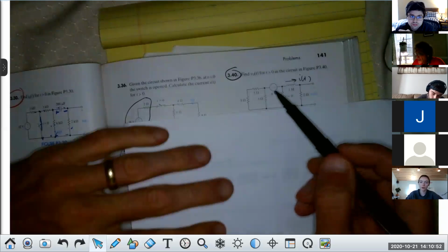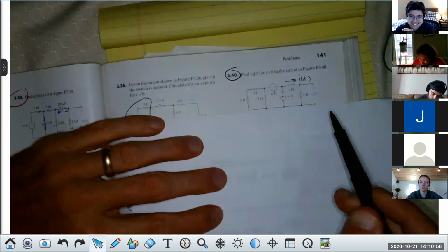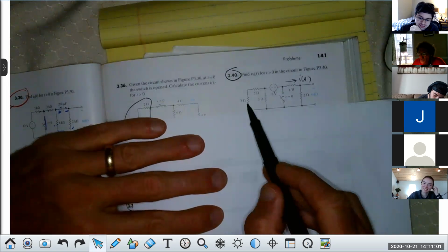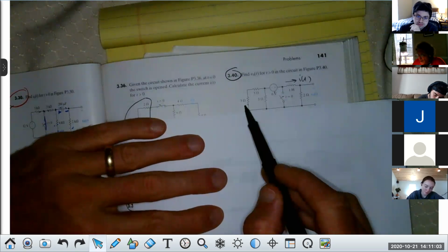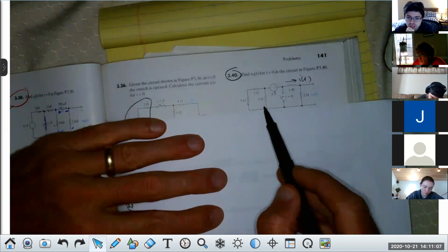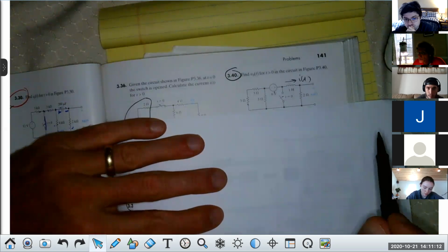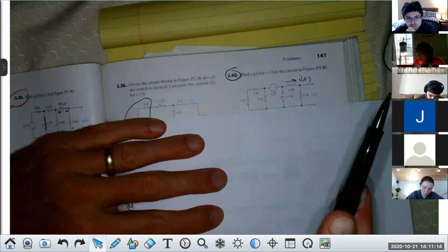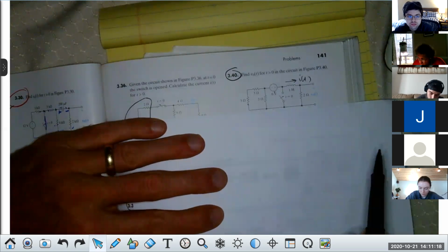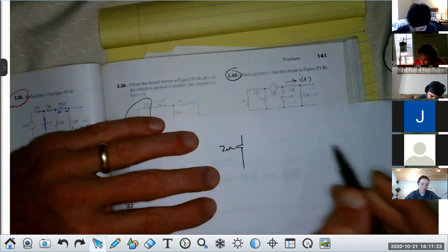The more heads that are actually alive, the better. Jessica, I don't know what's going on, but thank you for your thumb. That's good enough. If I see this, I'll make that 6 ohms. Do you all see that? I have 6 ohms. Do you all see it's in parallel with 3? So if I have 6 in parallel with 3, isn't that 2? 6 times 3 is 18. 6 plus 3 is 9. 9 into 18 is 2. So it's 2 ohms. That whole thing right there is 2 ohms. Just start with that, reducing.